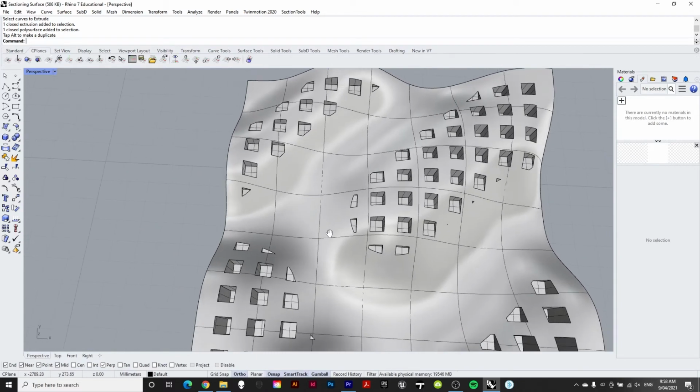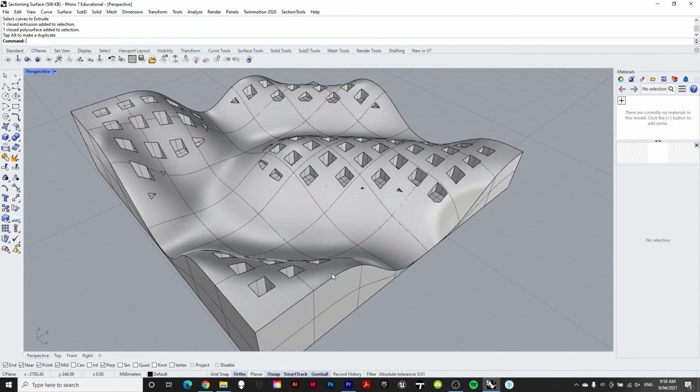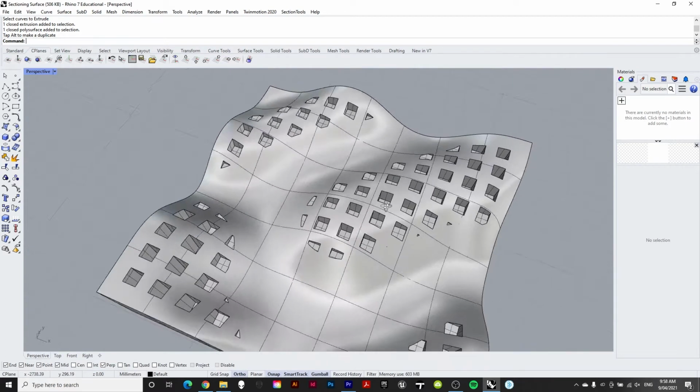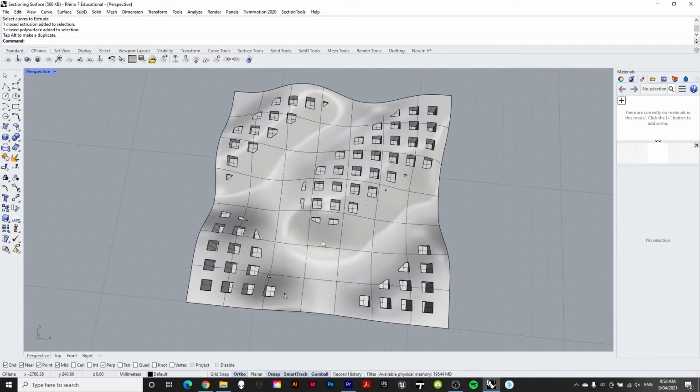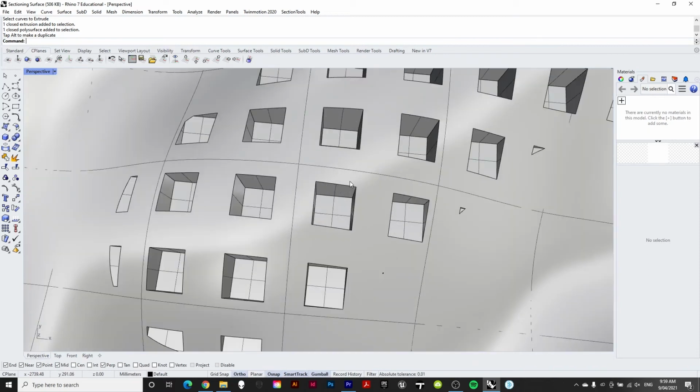Alright, so here we've got a bit of a wavy surface that you could imagine if this was one solid block. Then we carve all of this stuff out, we'd be left with this. And we've got some indentations inside there, so maybe this is a new type of acoustic panel or something like that. What we do need to be cognizant of though, is that when we go to a CNC, we're going to lose some of these sharp corners because of the nature of the process.